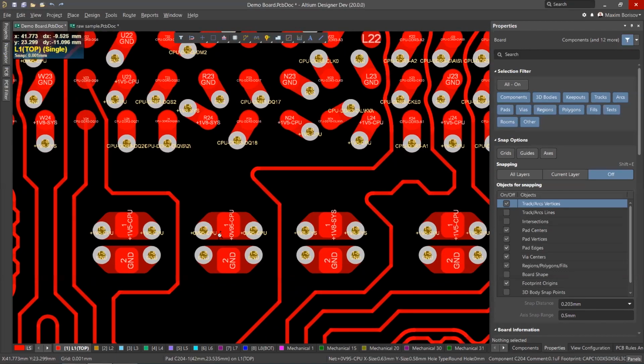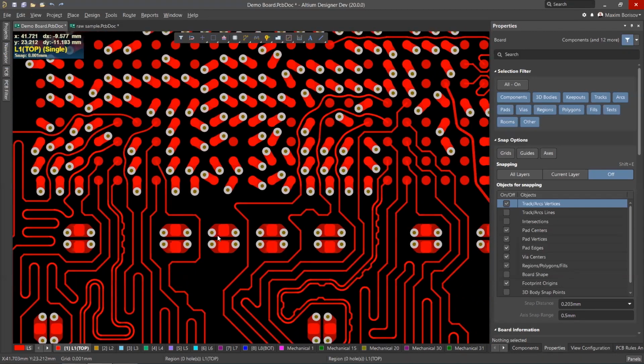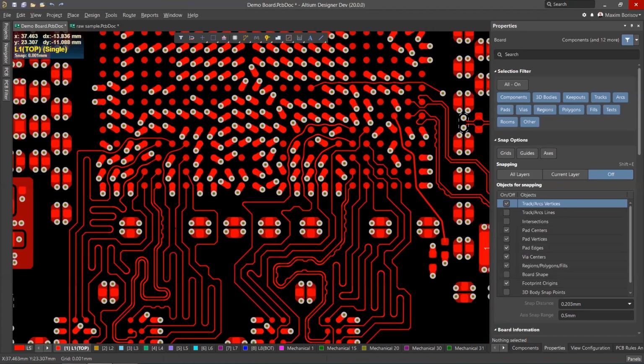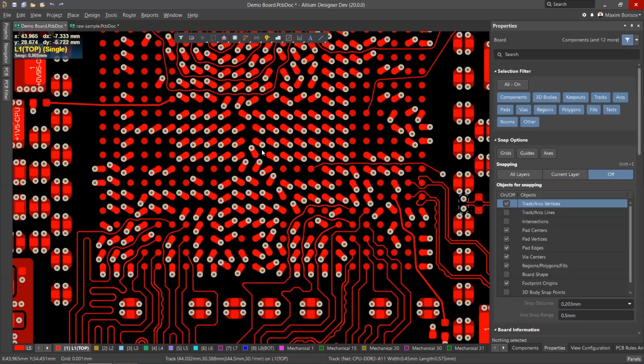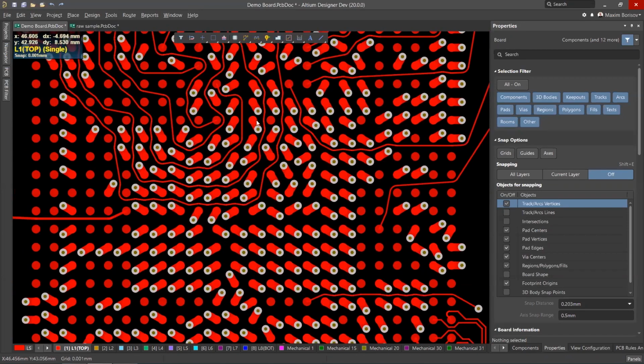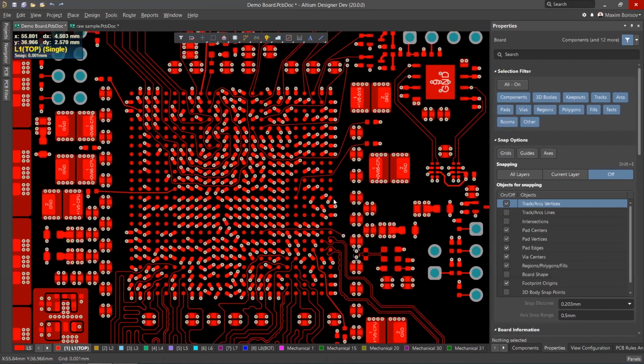You have quite some place to drop, let's say, low inductive fan-out patterns and still maintain sufficient headroom for length tuning, other kind of routing, everything you need. So there are tons of benefits which usage of such functions may actually bring into your everyday design routine.